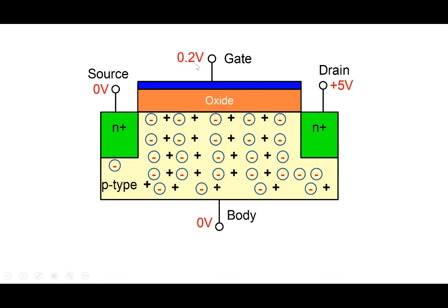All right, so when we apply a positive voltage here, note that what it will do is, this positive voltage will create a field pointing down into the semiconductor and will push away the holes. The holes are mobile and they'll react to the field and will be pushed away. And the positive charge will come and sit over here. So this region will be depleted of holes, and you create a depletion region because the positive charge has been pushed away. And so this region becomes charged. It leaves behind the ionized acceptor atoms here, negatively charged.